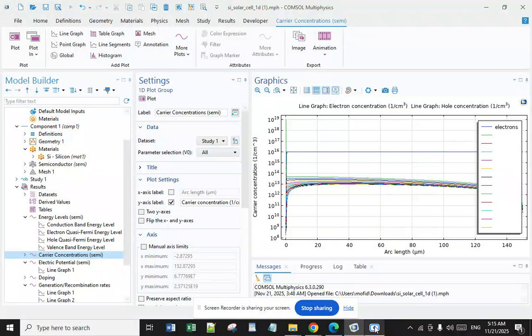And what about the multi-contact designs placement? Both positive and negative contacts are placed on the front surface but with a different design. The advantage is that it is more efficient than front contact cells, and the disadvantage is that it is more complex to manufacture than front contact cells.